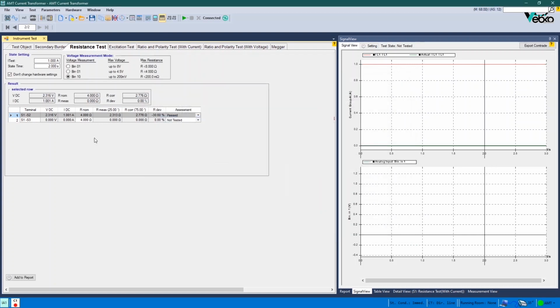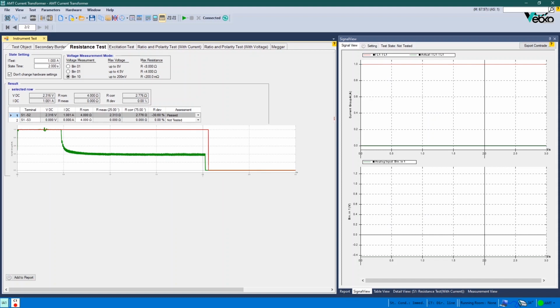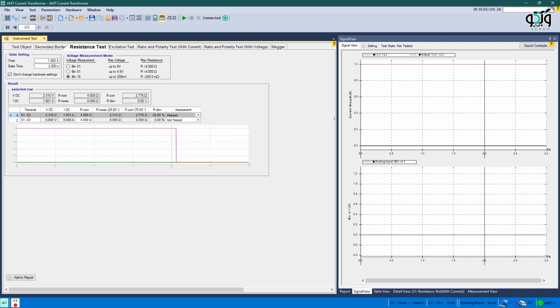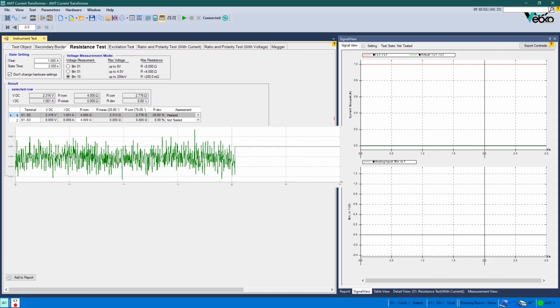Two notable points are that Error Other shows that there is a problem in the wirings, or the resistance is too high so that the device is not able to provide the burden to inject the current. Therefore, if this error appears, examine the actual value of the current in the Signal View. If the current is injected, but its difference from the set current is too much, the wiring resistance is too high, and if the actual current is 0, the route is open. If the resistance is too high, the current should be decreased, and if the actual current equals 0, you need to examine the connections. The other point is that if the measured voltage is 0 or has too high tolerances, it means that the connectors are not connected correctly.